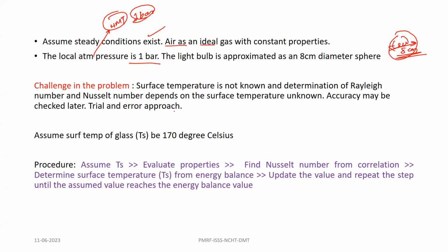Okay. But the one challenge in the problem is the surface temperature is not known, because we need to determine the bulk fluid temperature, TF equals TS plus T infinity by 2. Only then we can determine the properties at TF.